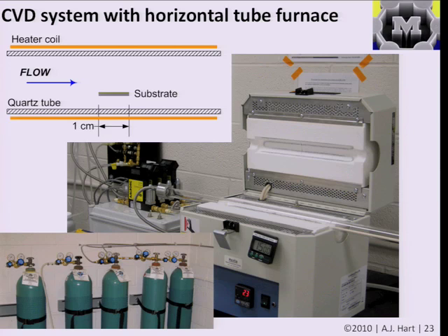So if, for example, we were operating in the first case where we had a vapor of a metal, we could, for example, deposit the metal on the substrate. Or in the second case where we had a chemical reaction we wanted to happen on the surface, we could bring in some precursors. They could react at the surface with whatever's there. Maybe we would form nanoparticles. Maybe we'd grow nanotubes and nanowires. And then you would have the products on the substrate and the things that are left over from the reaction, and they would issue out the opposite side.